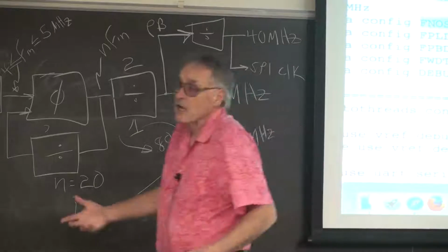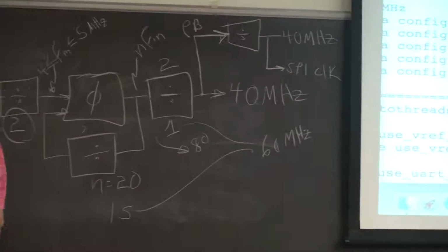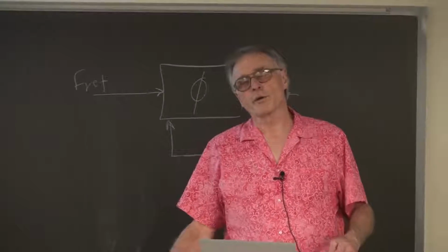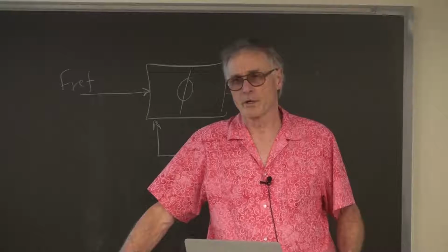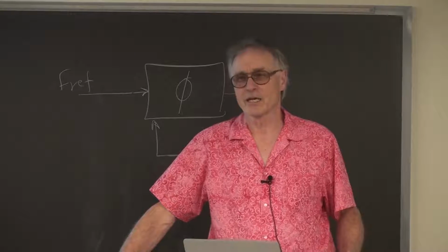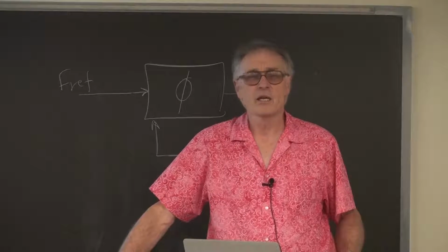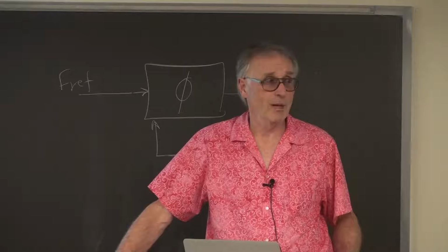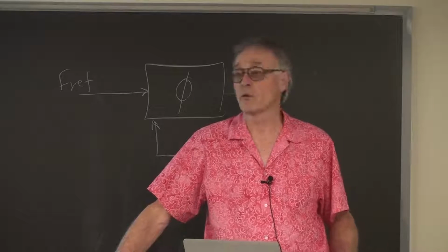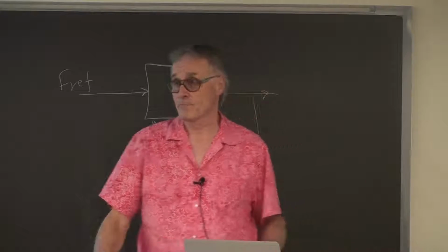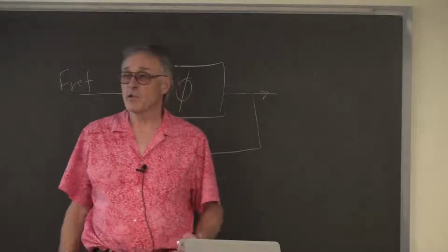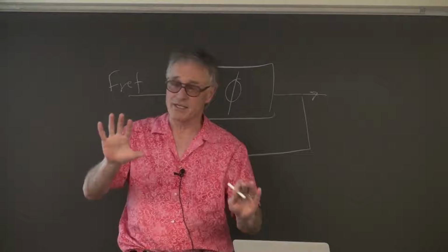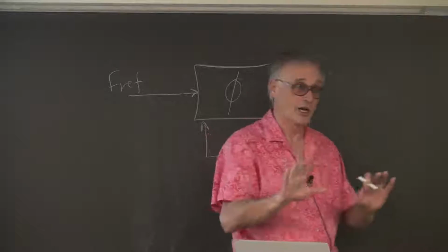You could see how fast the SPI will run. If you built a solder board and avoided the whiteboard, you might be able to get 30 megahertz out of it, although I believe that the DAC is only rated at 20. It might work at 30 anyway, but it's only rated at 20. So you're going to have to do some sort of optimization in PLL space to make this work.